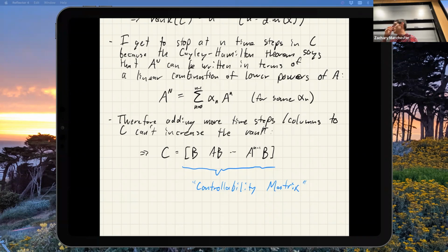That sort of analysis is actually what you have to do in MPC problems with constraints. So in linear MPC, this idea comes up a lot. You think about the subspaces that you can stabilize in certain time horizons given constraints. In general, for linear systems with linear bound constraints on the controls, you can write these down as polytopes, and there are ways to look at that. So that's a thing when you analyze MPC with a finite horizon and constraints.